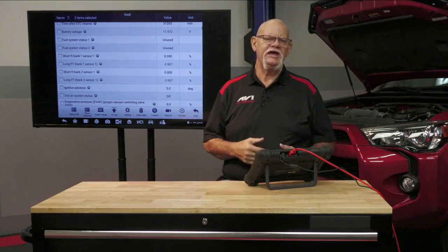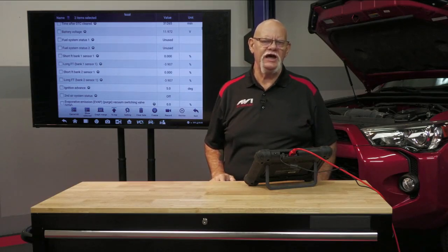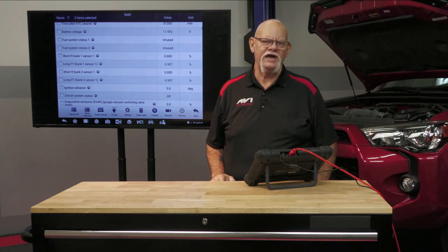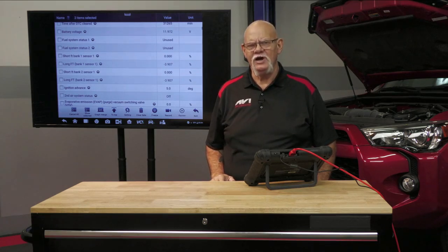For example, let's say that my fuel trims long-term at idle are 18% positive. But as soon as I crack the throttle and start into a cruise, they fall to 8%. 18% is out of spec. 8% is in spec. Why would the computer need to add an additional amount of fuel at idle only? It's a dead giveaway. I don't even have to tell you a year, make, and model. You better start checking for a vacuum leak. If you use your smoke machine to find that, then get it out and go after it.